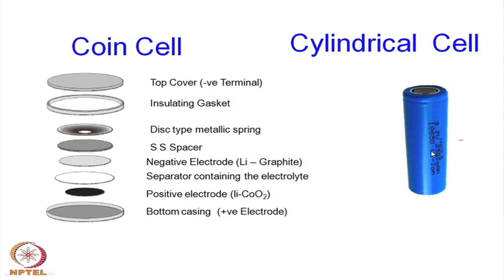Of course, there are very different kinds of shapes of lithium cells, like many other rechargeable batteries. The standard kind of battery here is cylindrical. Here they are produced in a completely different manner. It is very similar to the tape casting process. So there are rolls of three different sheets: the cathode, the anode and the separator.